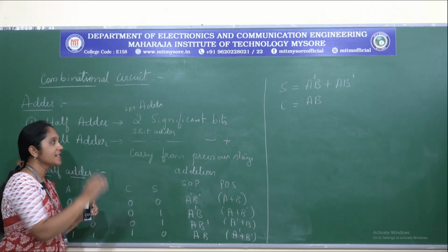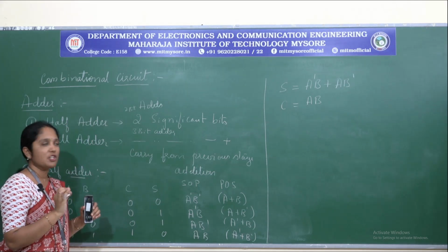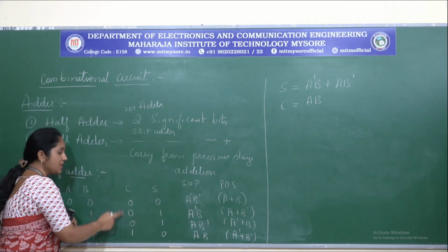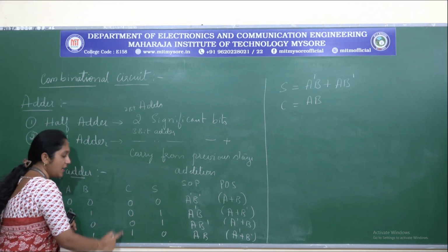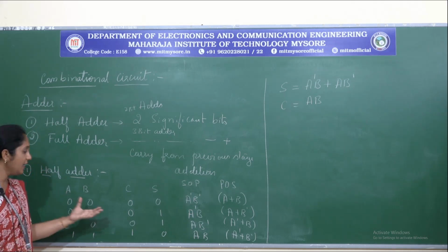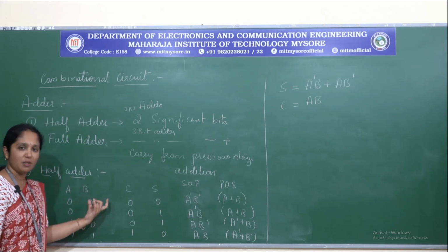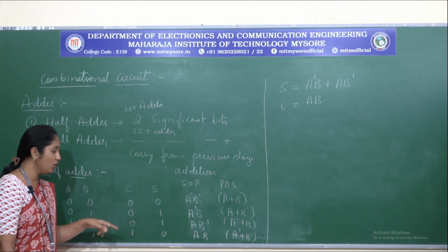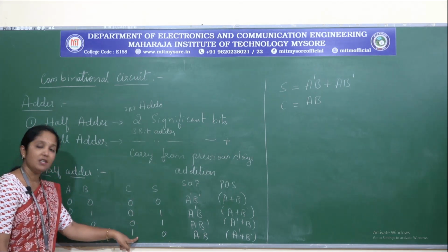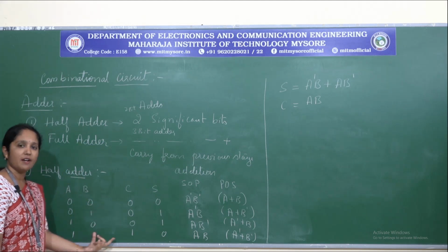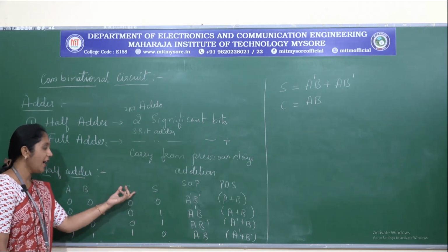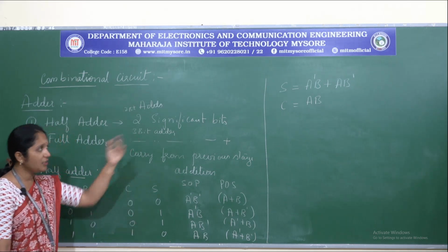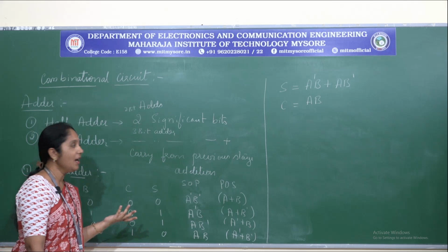So this is the first equation we have obtained. Now if you observe carefully, you can notice that this carry is representing an AND gate, because for all these input combinations we get the same output pattern as an AND gate. We know that the output of an AND gate is logic 1 only when both the inputs are 1. Therefore, the carry can be replaced by an AND gate, and there also we have A B, which is nothing but an AND gate.